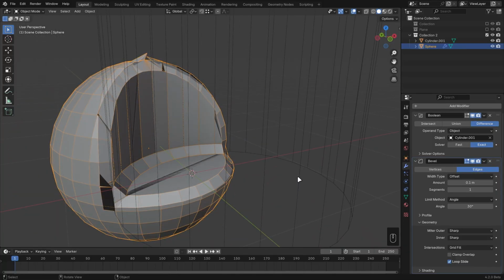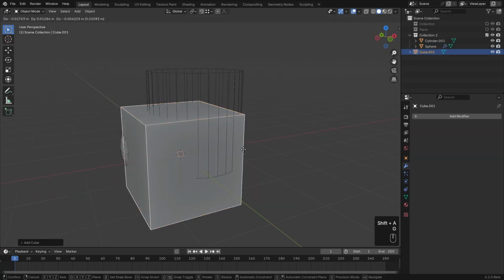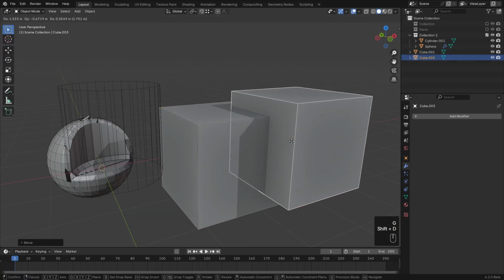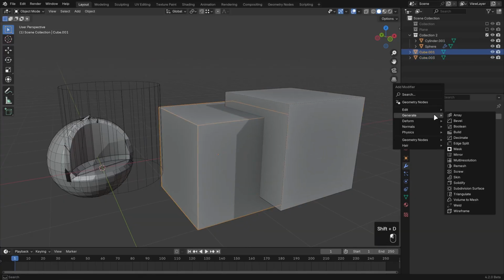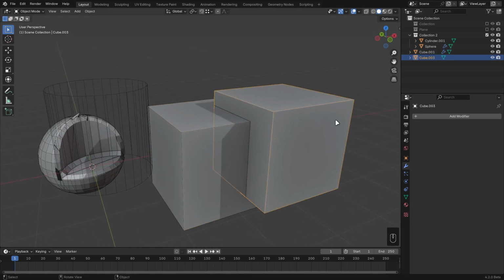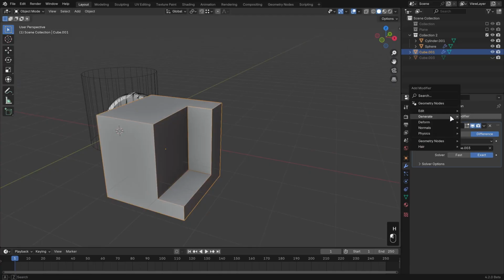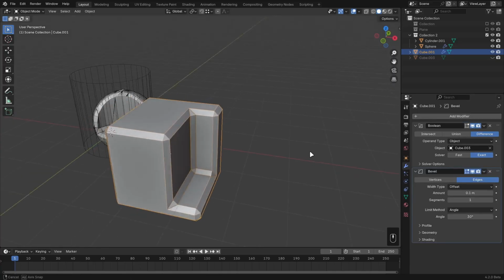This is because the mesh that we get from Booleans is often very messy. So one thing that you might have to get used to doing, if you're working with Booleans, is going in and cleaning things up manually. Now with more simple objects, you don't have to do that. For example, if you just have some cubes, like so, and let's Boolean one from the other. Let's go from Boolean, select this second one as the object, just like so, and then I'll go ahead and hide this second one. If I take this, I can go ahead and add a bevel modifier, no problem.